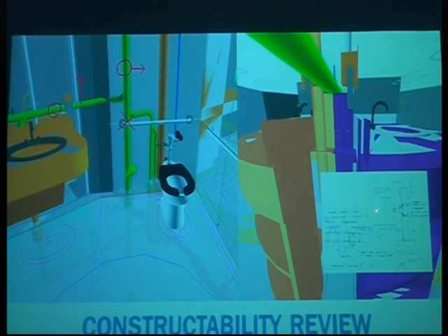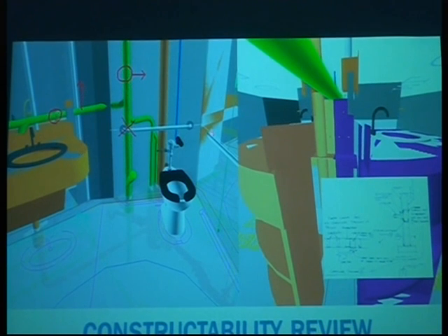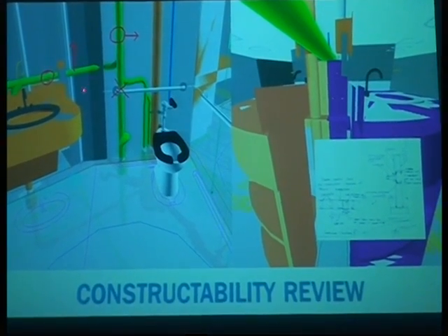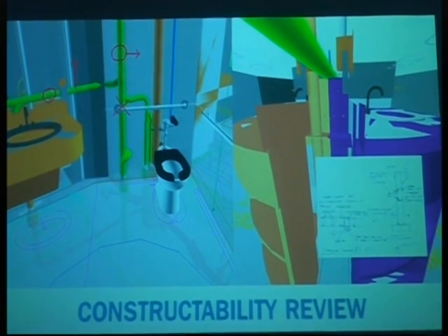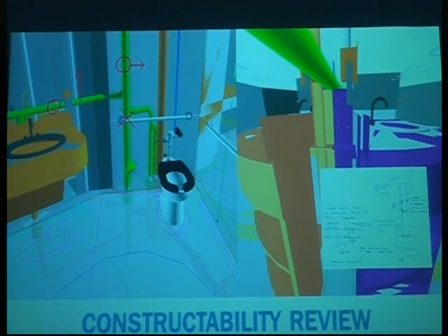And so even the architect, the designer, these are things that they don't see, essentially. And so our recommendation for them is that this riser needs to move so that there is no conflict with the grab bar. Otherwise, if it was installed, we would have an issue, right? That pipe would have been punctured. And we would have a big mess, and this is a hospital.